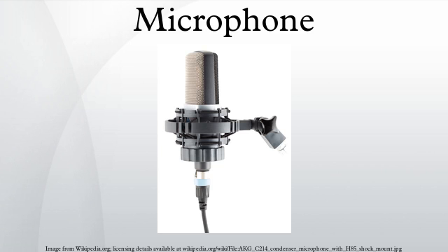Other elements such as the external shape of the microphone and external devices such as interference tubes can also alter a microphone's directional response. A pure pressure gradient microphone is equally sensitive to sounds arriving from front or back, but insensitive to sounds arriving from the side because sound arriving at the front and back at the same time creates no gradient between the two. The characteristic directional pattern of a pure pressure gradient microphone is like a figure 8. Other polar patterns are derived by creating a capsule that combines these two effects in different ways. The cardioid, for instance, features a partially closed backside, so its response is a combination of pressure and pressure gradient characteristics.